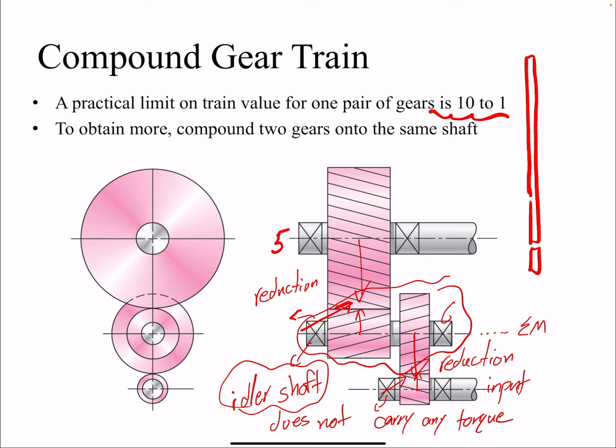You can reach these ratios, let's say 1 to 30, but not with spur or helical gears. We can reach that with worm gearing. A worm gives us a high velocity ratio. So you go from a worm, which technically has 1 tooth, to a gear with 30 teeth. So you get a ratio of 30. You're increasing the torque 30 times.